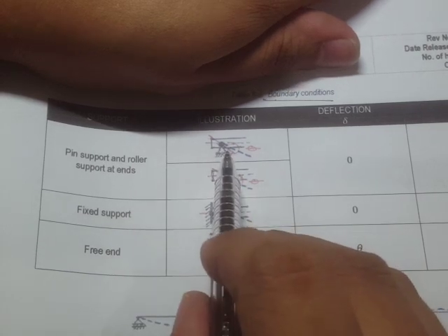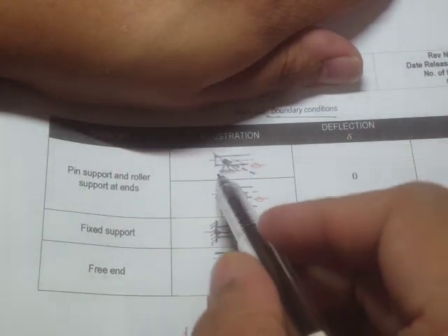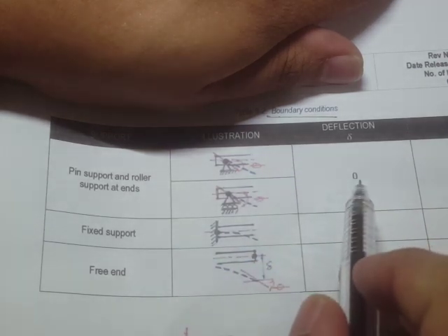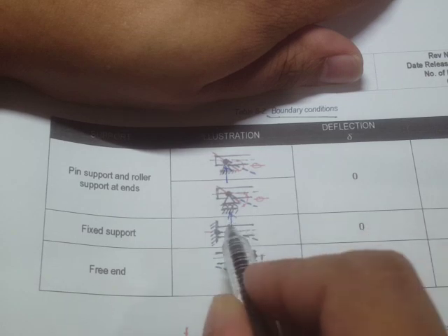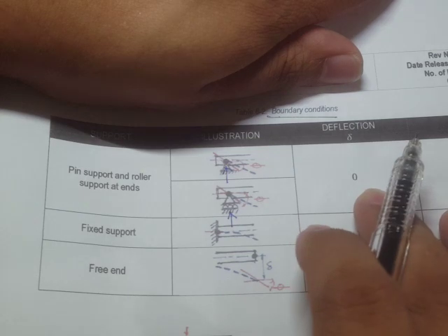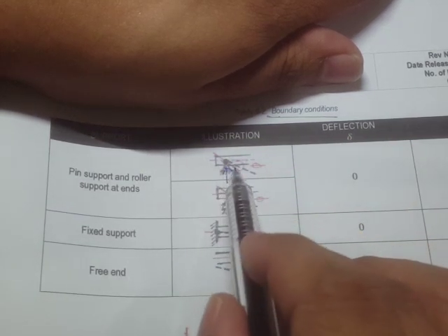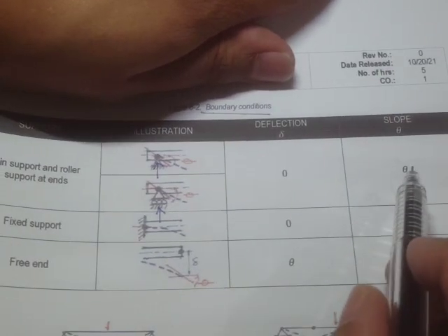Now let's talk about these deflections and slope at the supports. If we have a pin support or roller support, then the deflection, the movement along the y, only the y, the movement of this point is actually zero, because we have a support reaction right here, right? There's a vertical support reaction, so therefore it doesn't allow any deflections. But for the rotation, because pins and rollers allow rotations, there's going to be some value of the slope.